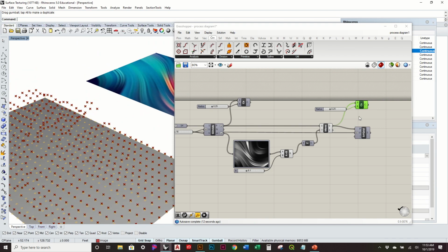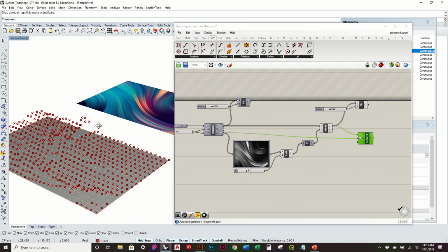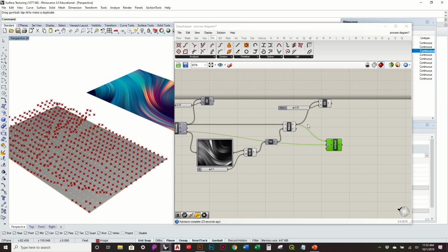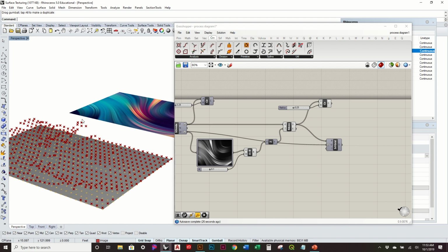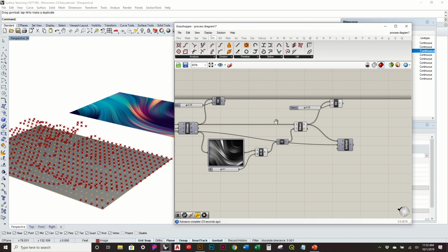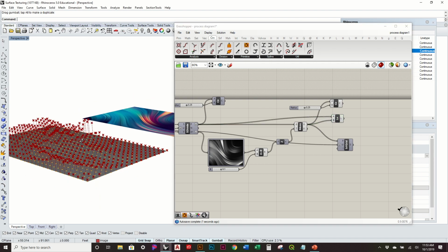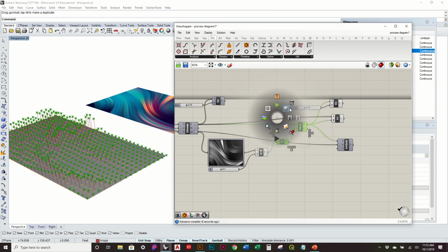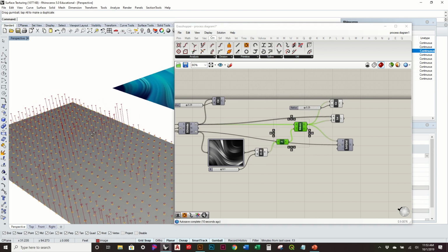And so something else we might want to show, instead of just having them at their different heights, is that they moved different heights. So another kind of visualization, because it might be a little difficult to understand what those elevations were. What we can do is create a simple line that goes from the original points, which was here, and our new points. So now I've got some curves associated with that. So I can turn this off so I can see it a little bit better.